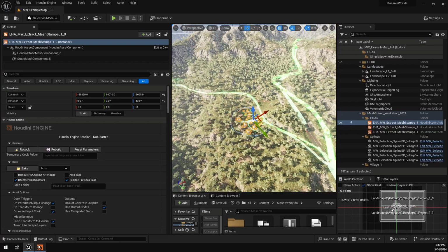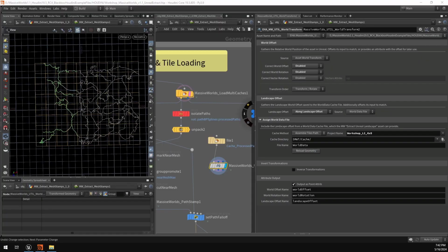But if we're working in Houdini space, then you might want to work in a centered space, or in a space representing Unreal world space without the offset of the asset itself. Whichever correction you want to use, I found this node can do all of them. It's just a matter of trial and error and finding out which combination of offsets each type of input that you're feeding to the tool uses, and then how to correct for that using the World Transform node.